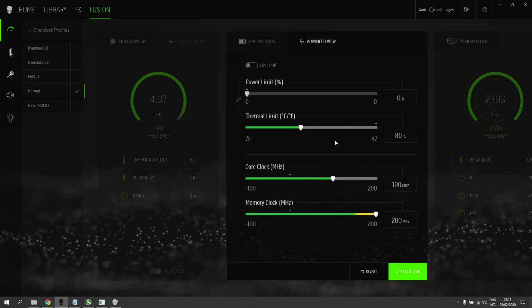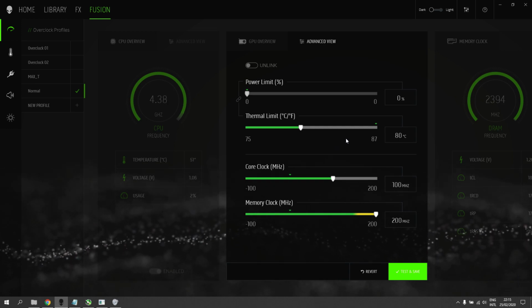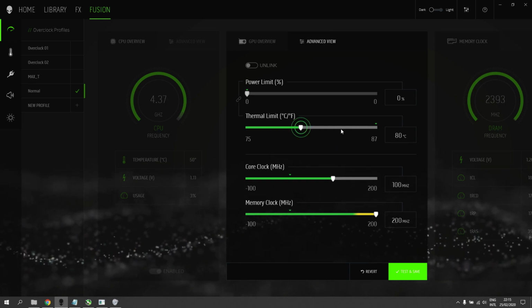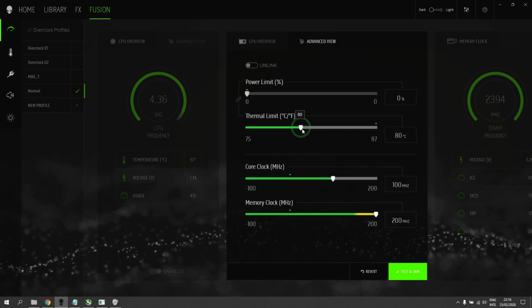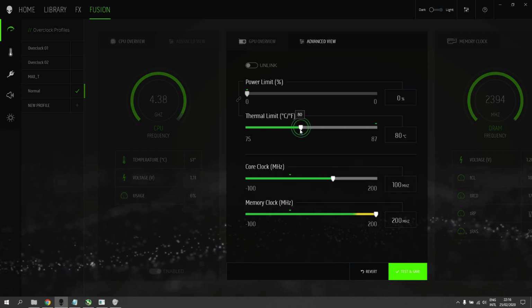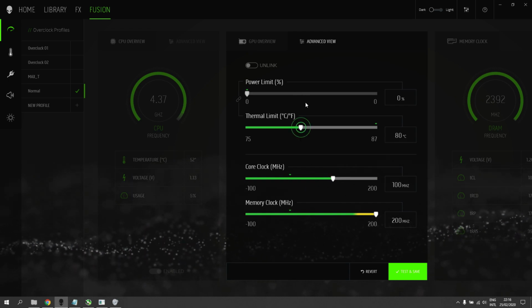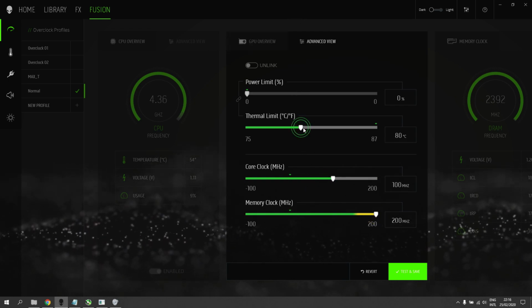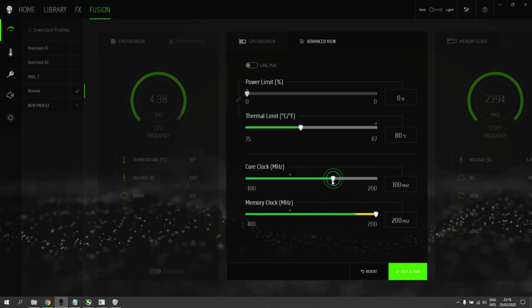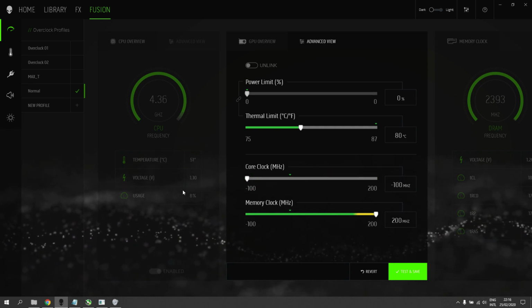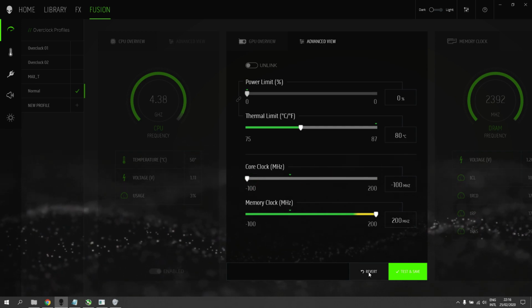The BIOS says, uh-oh, we're in the red zone. I'm going to downclock the hell out of it. And even for that 1 millisecond of the spike, if it bypasses the hard threshold, your GPU will clock all the way down to 300 megahertz. We don't want that.